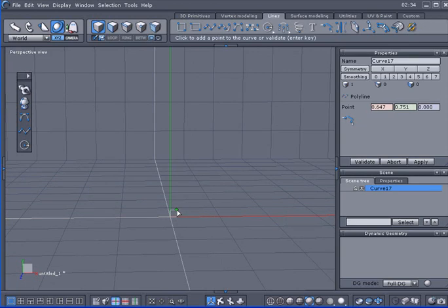Now this ain't always accurate. It will snap to this floor grid pretty close. It's not real sensitive. So if I click here and hold the shift key down, the crosshair comes up, but it didn't snap to it. Look at the parameters on the right till I get closer. Look at them, they're 0, 0, 0.